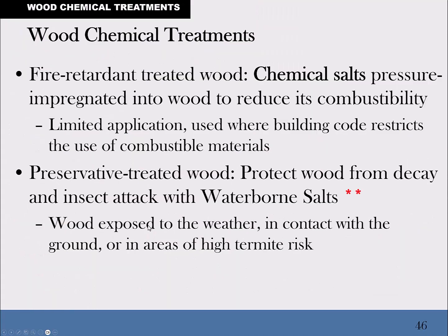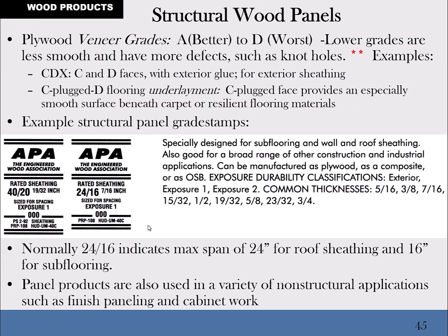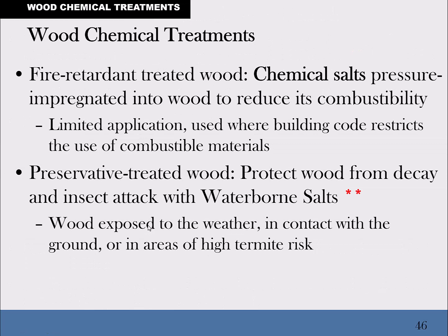Oops, lost my page here. Okay, so let me skip along here. Wood treatments. So there's fire retardant treatment you can get. There's a chemical salt that is pressure treated into the wood. Pressure impregnated, they're calling it here, but it's pushed into the wood surface under high pressure, usually in a vessel.